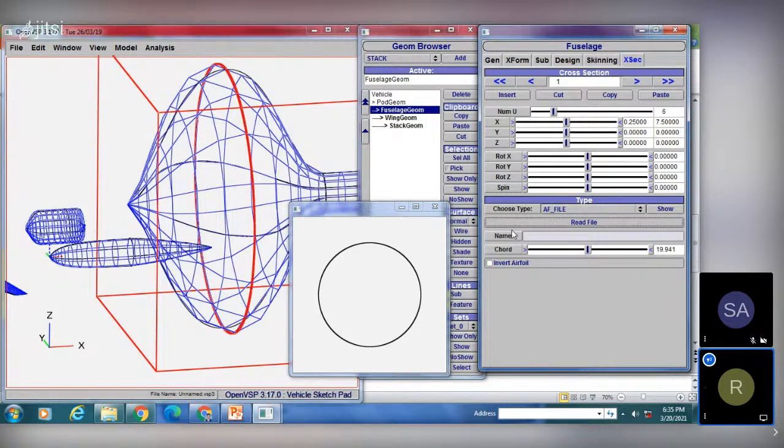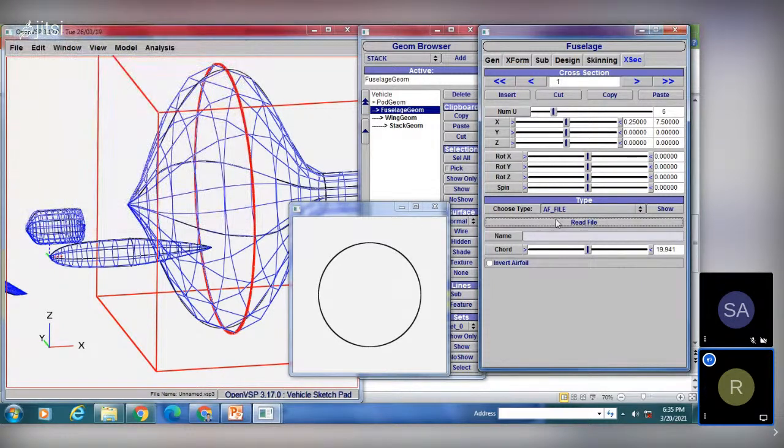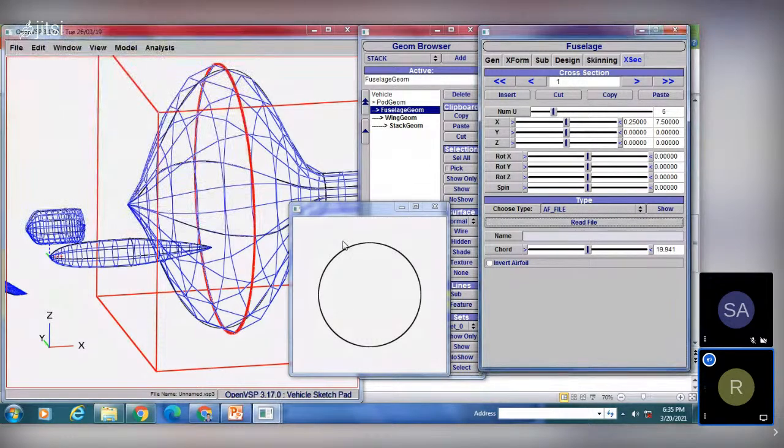By default, the baseline thickness to chord ratio will be calculated and set for the section. However, you may also alter this thickness to chord if you wish. You can create a new aerofoil based on the original profile or the original preview. The camber line is conserved in this case. Detailed information about the AF file format can be found on the programming tech website. Which means if you have a program-related AF file that you have created, you just read that file and add it here, like an aerofoil database and all like that.